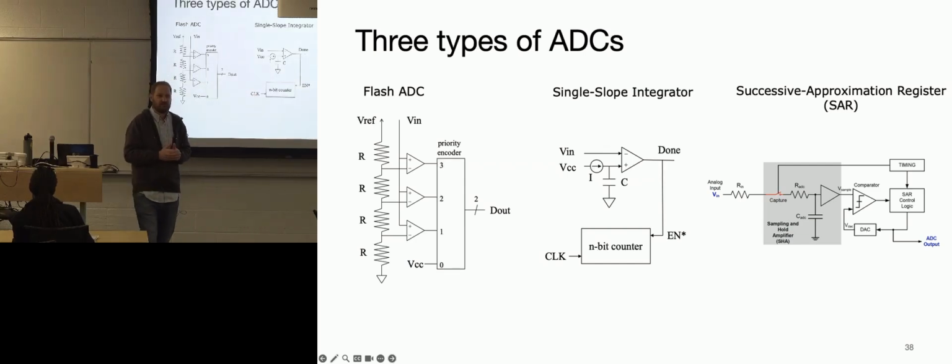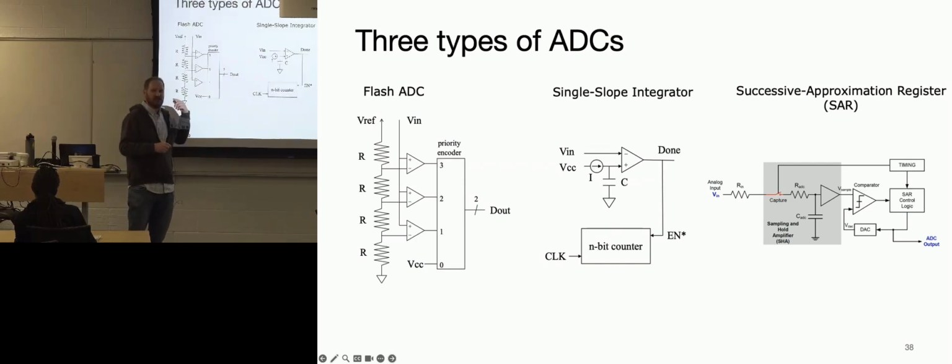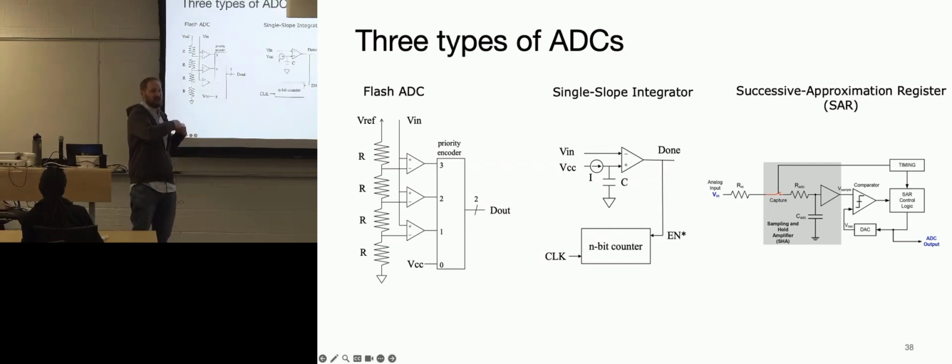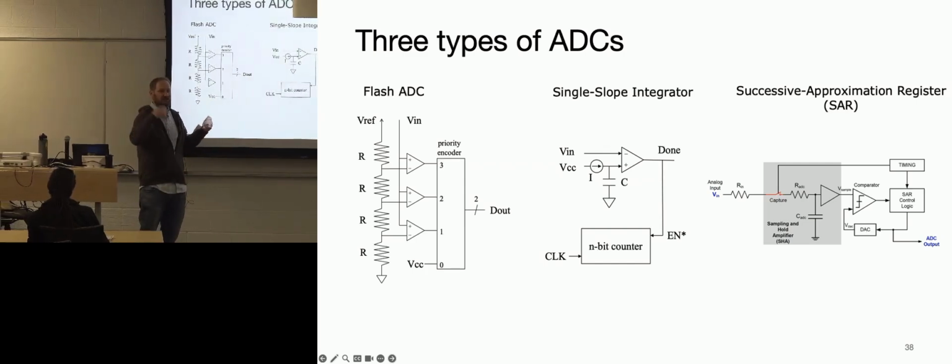Interrupt early, because it already has the value? It could do that. You could add logic to do that. But the reality is, because the hardware doesn't know, returning an interrupt early doesn't actually solve anything. Sure, that sample itself can be faster, but later on, say you're trying to stream serial data through, you're still going to set up a timer on some rate, assuming the worst case scenario, so your sample rate is based on your worst case conversion time. So for your particular microcontrollers, they don't throw off an interrupt faster because of that.